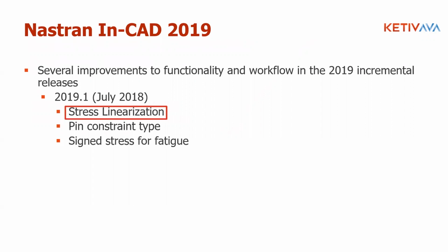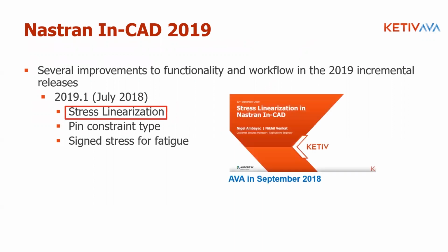Now, one of these, stress linearization, we actually covered in depth in September of 2018. We did an AVA on that specific topic. If you're not familiar with the concept of stress linearization, it's something that's pretty useful in designing pressure vessels, and it helps you specifically compare your FEA results with the pressure vessel code.